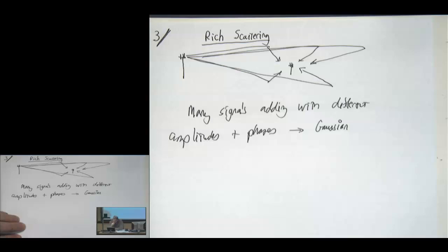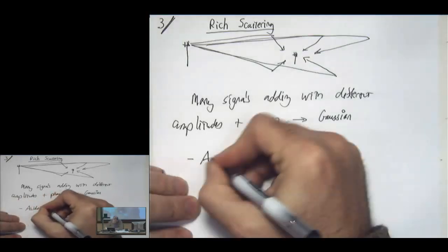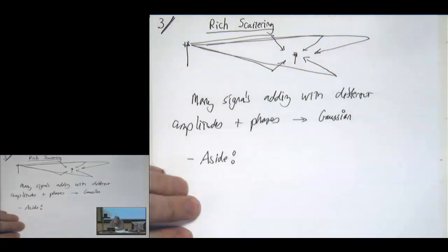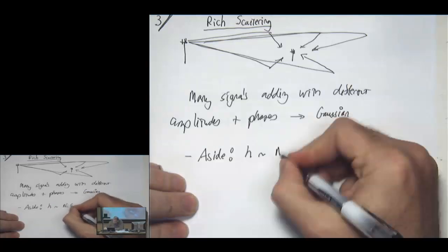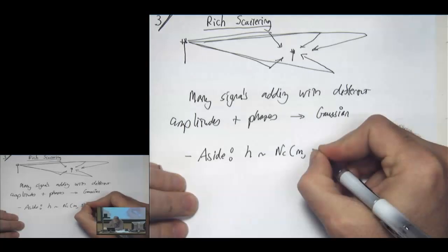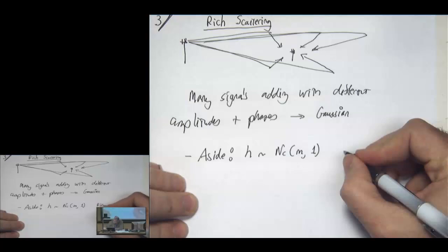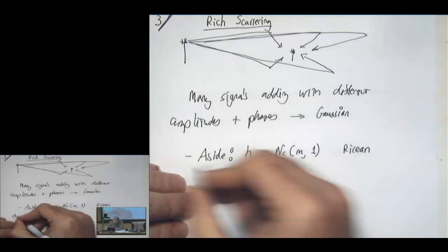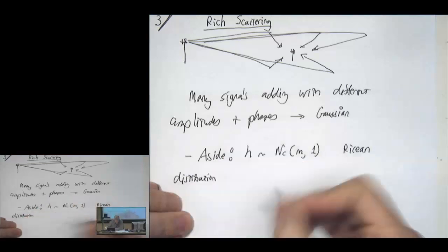So with that, actually I forgot, I wanted to say one other thing here, which is that there are some other distributions related to Rayleigh. The one that's most closely related, and we might see this one in the homework, is the case where instead of having zero mean, you have a non-zero mean. And the variance might be 1, or the variance might be something else here. This channel has a name, it's called the Rician channel, because the envelope has the Rician distribution.